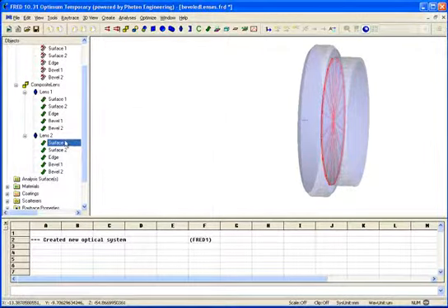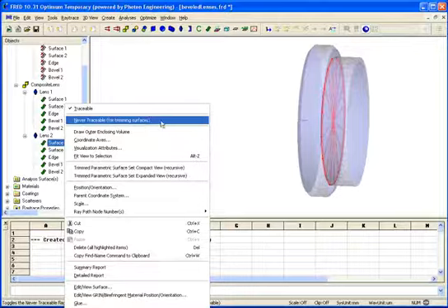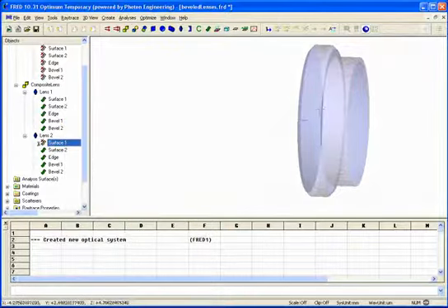I'm going to go ahead and right click and toggle it never traceable for trimming surfaces. And that means that a ray can pass right down the gut of this composite element, intersecting only the first surface and the back surface of the second element. So there's no intersection in the middle of the element, which means that it goes air to glass, travels all the way through, then glass back to air. And this will account for all of the possible material combinations through this lens system.